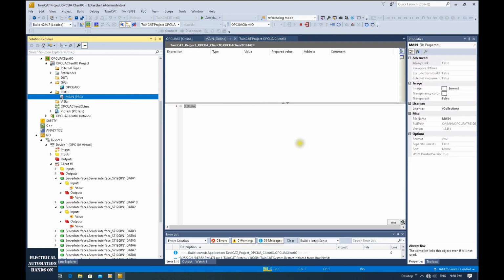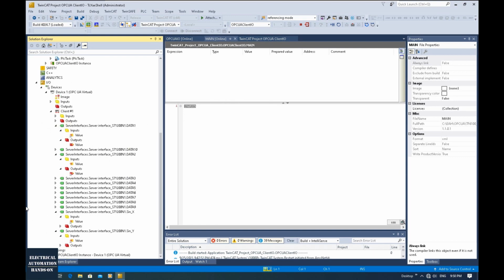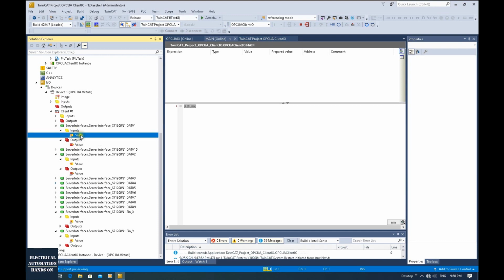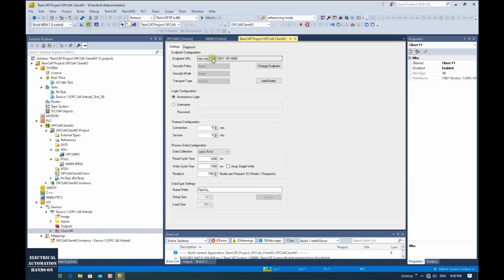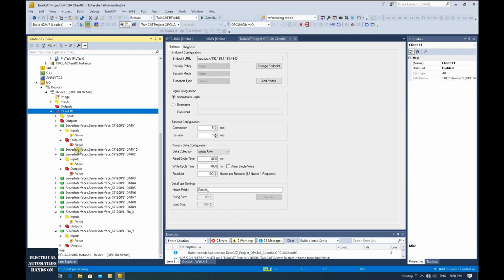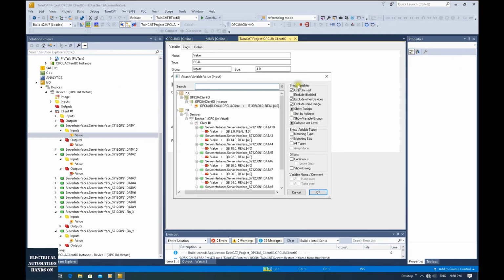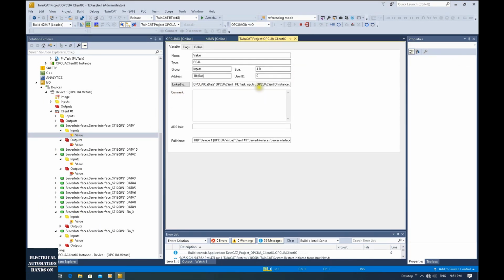As we can see, we do not need to program any OPC UA Connect, read or write program. We just did some configuration here. Also, from the OPC UA server side, we just need to do some configuration and use the link IO method. We can set up the OPC UA client function. And here, we set up the connection for the IO. We can use the link IO, allows these 2 different PLC, they can exchange the data.